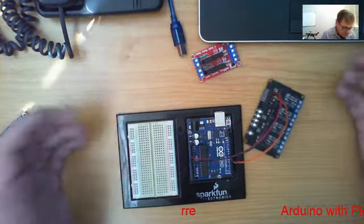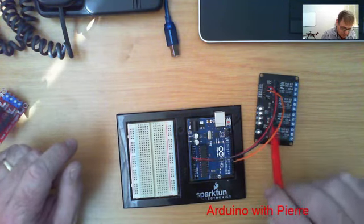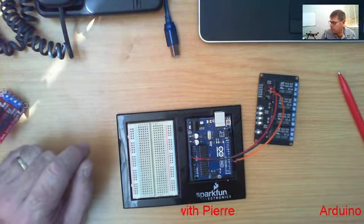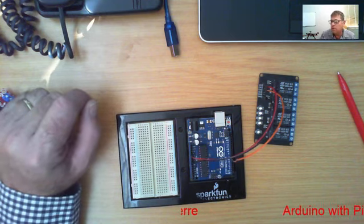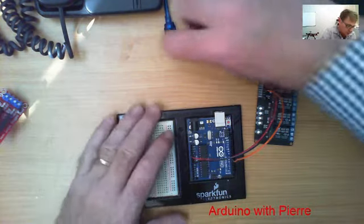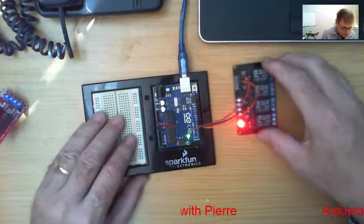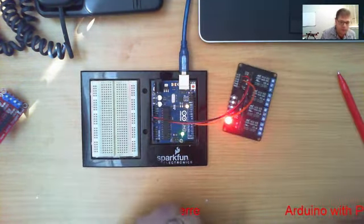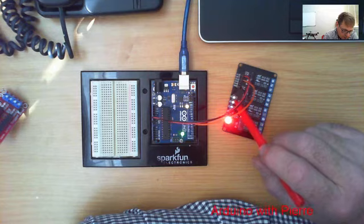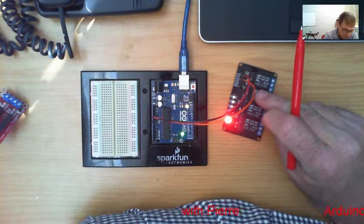So that's how easy it is to use these boards, because they've already got their transistors, they've already got their flyback diode, they've already got the LED indication of that. Alright, so what you can do then is just compile and upload your sketch. So remember that sketch of ours will switch the relay on and off every 1 second. The sketch is already on the board, and you can see there that LED indicates that relay number 2 is switching. If I touch it, I can feel that it's switching.